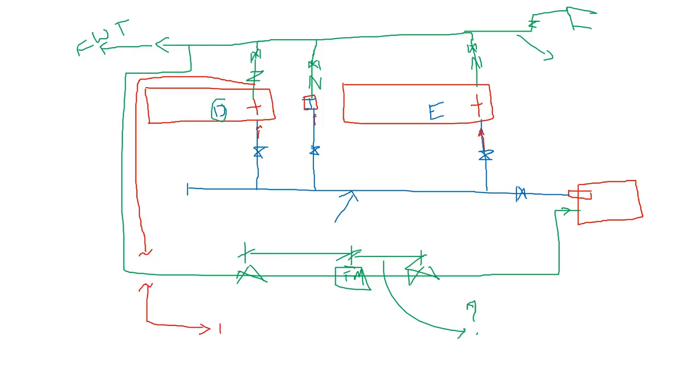You need to make provision if this line is taken to the tank. You need to make some sleeve in this water tank in order to connect this pipe to the tank. The overpressure relief line basically has a pressure relief valve and waste cone. So now the chapter is closed about the piping.